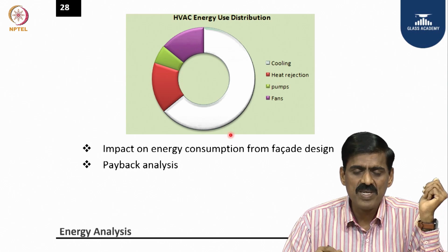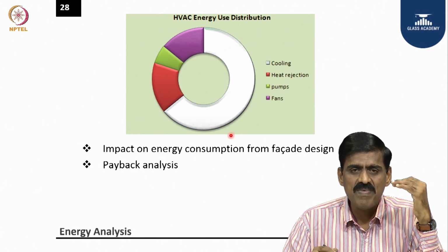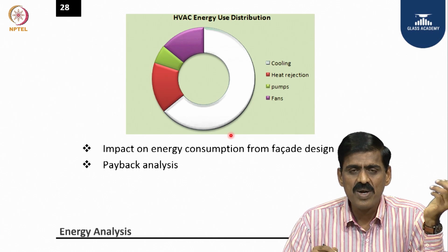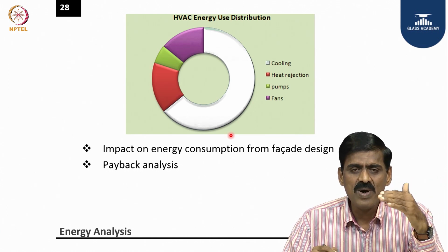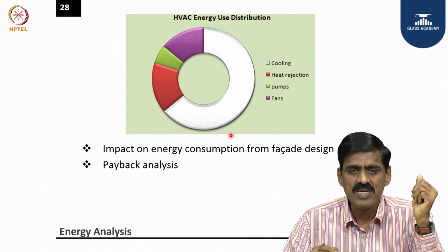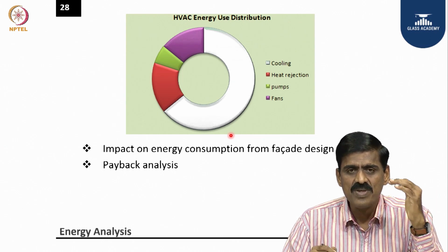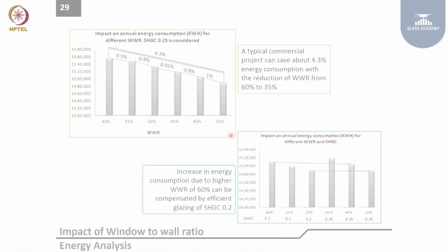Then you adjust your facade accordingly. There's always a saturation that comes. Beyond that, people can ask, instead of 600 mm, why not 1200 mm sarja, or why not 2000 mm? But beyond a certain limit, saturation occurs. So you have to stop there, then get into the cooling design so that you can optimize overall cost.